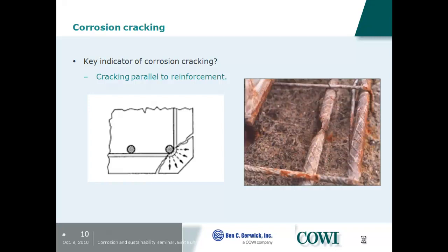Again, normally we have cracking in parallel to our reinforcement, but sometimes if you have a crack or a localized attack, you can also have reinforcement just completely disappearing in one location without visual signs of corrosion.